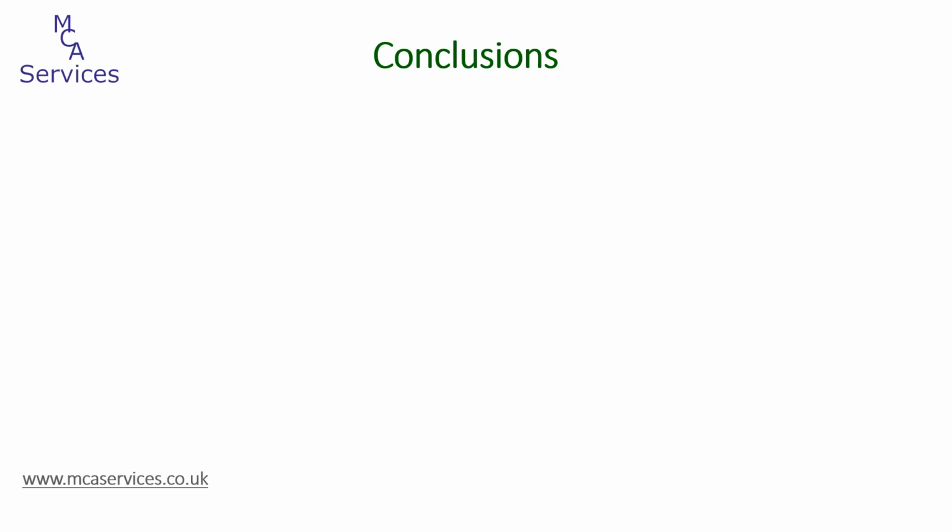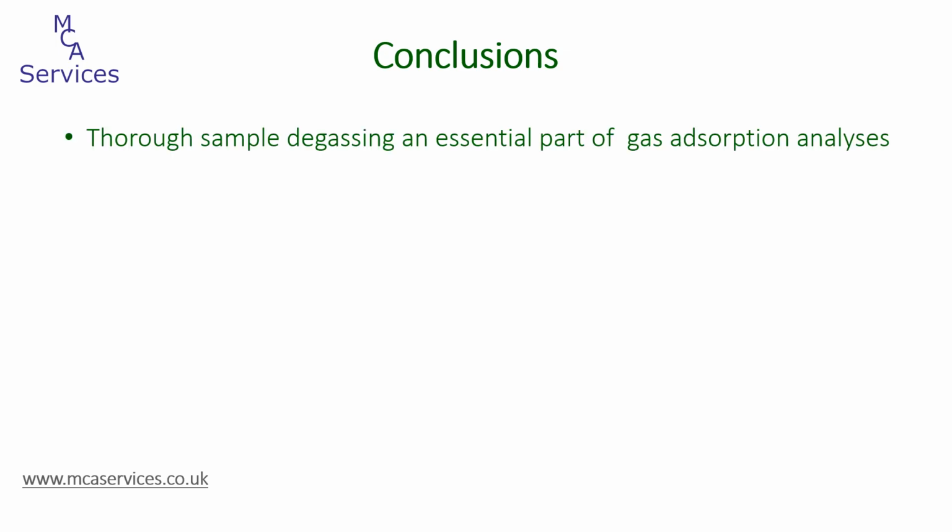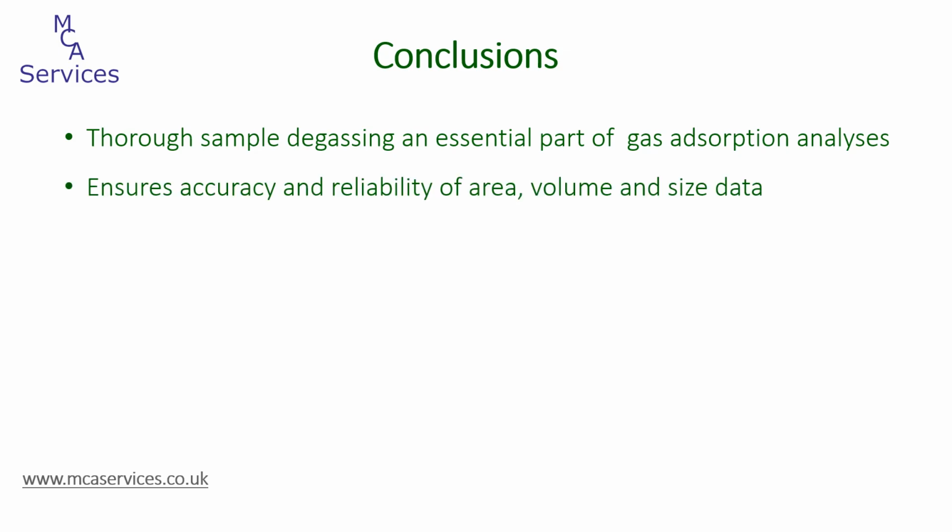So, in conclusion, sample degassing is an essential part of the gas adsorption analytical process. Complete degassing ensures that accurate and reliable surface area, pore volume and pore size distribution data are obtained. Pore size data are more significantly affected as pores become smaller or their size distribution becomes narrower.